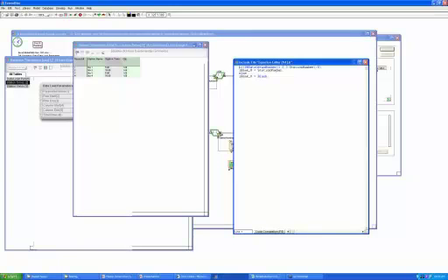With this queue being set, the lowest rank gets highest priority. This pushes the priority to station 1 and the lowest station being 5. In the case where there is no station available, the rank gets blank, and that does not allow any items to leave.